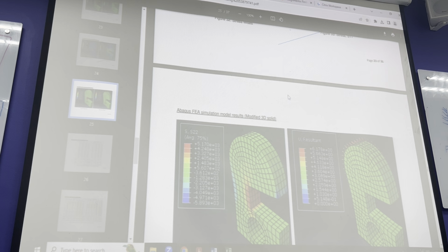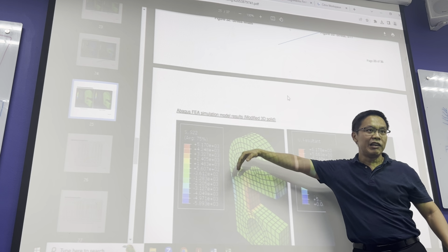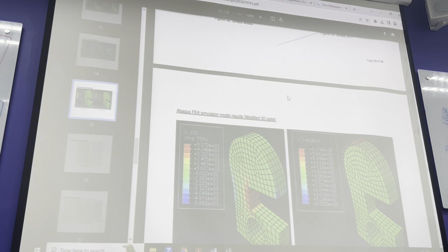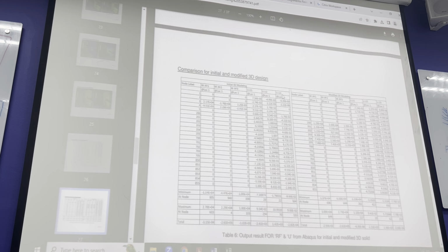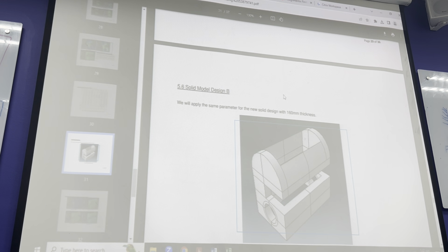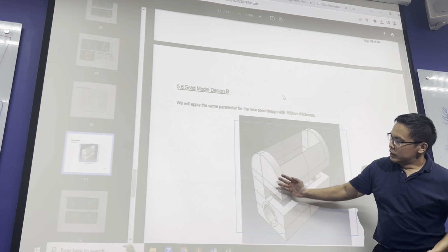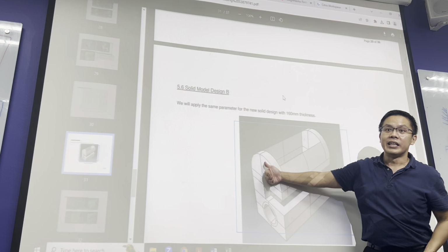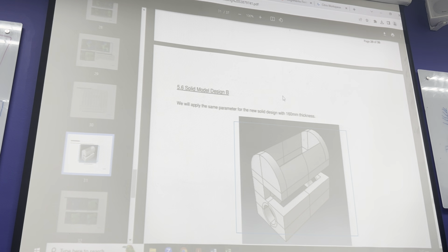That's why I say this is important for you to learn your software on your own. After that, refine the design. How do I refine the design? I do a curved cantilever beam so that I can increase material only when the cantilever moment increases. You're going to see the conrod even more. Refinement of the design. Then after that, cut through. Because I'm only interested in the bending stress in the thickness direction, correct? So actually I can remove some of the material here.